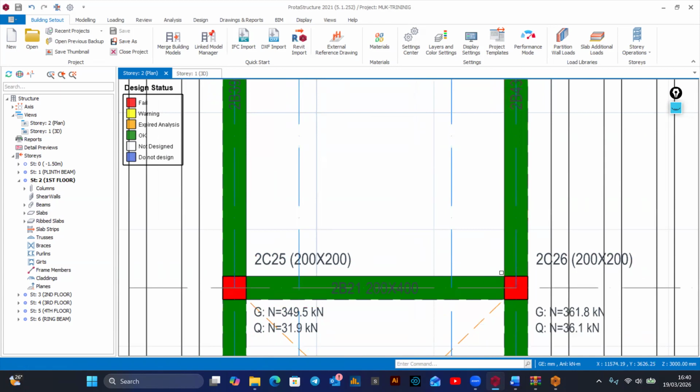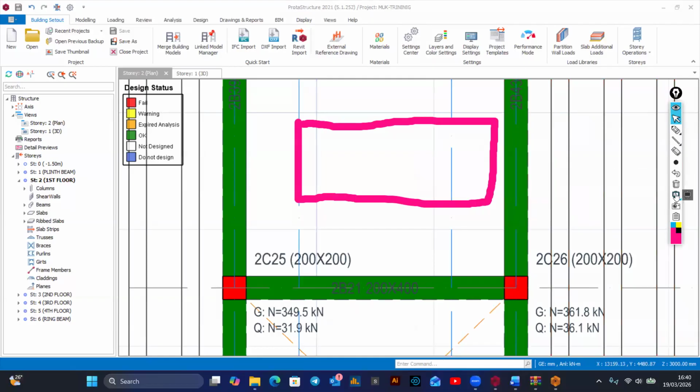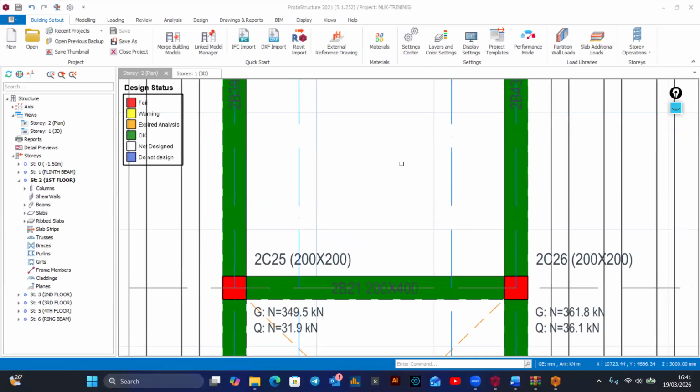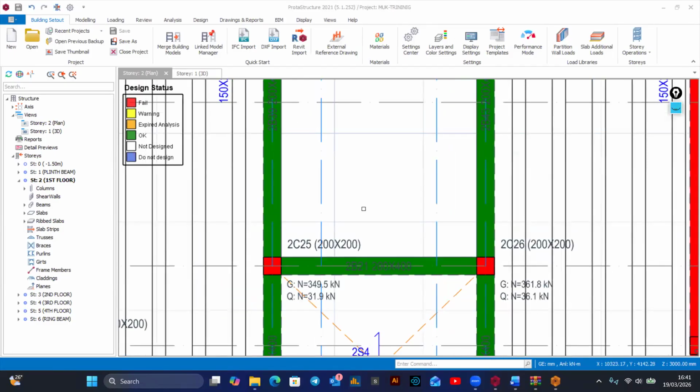Actually, at construction, it is very possible that you can even ignore that space in between. You just have stairs that are turned. You have this staircase coming, something like this. As this one comes, this one turns immediately without a space in between. You have seen this kind of construction before, just because of space. But in the program, it cannot allow that kind of behavior. So it is a must, you need to have a stairwell.